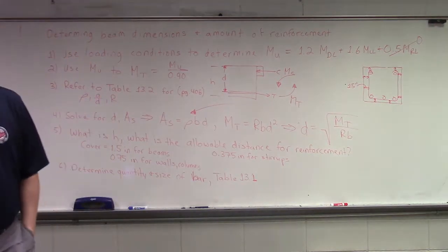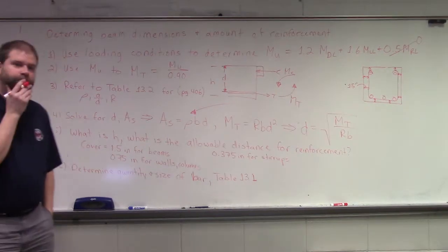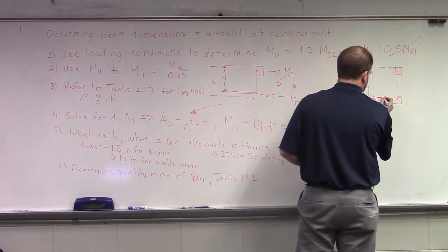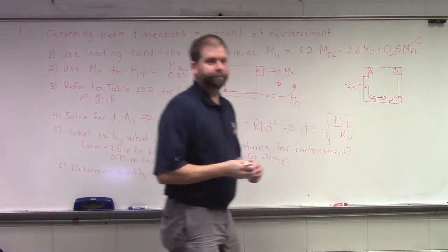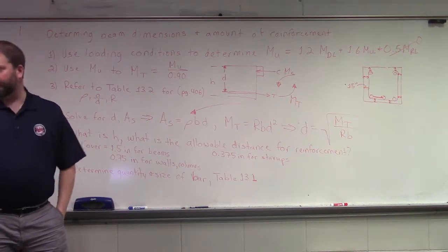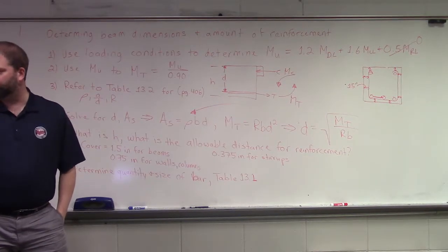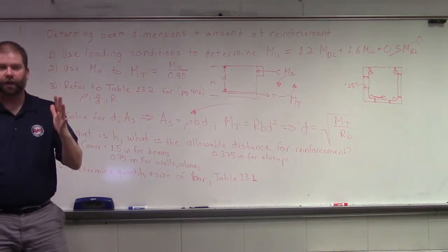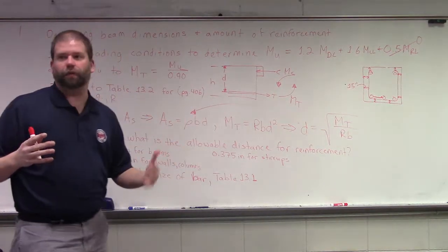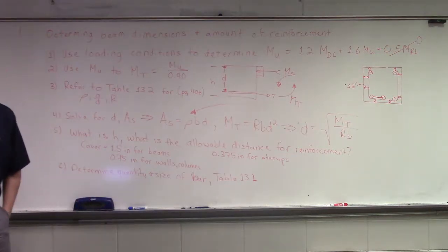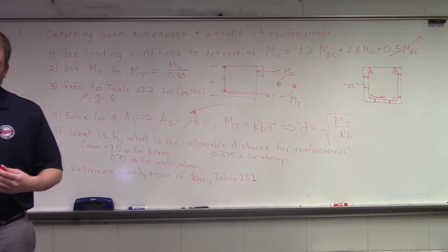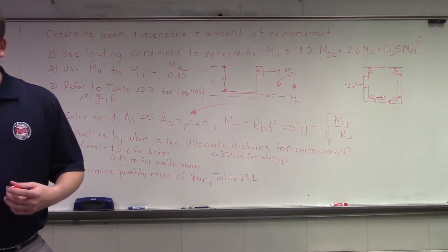So what Steve was saying is, whatever your bar diameter is should be at least your separation. Correct. Unless you're using a 3/8 bar or whatever. If you're using a tiny bar, you want to increase that distance. We want to increase that distance whenever we can, to make it easier for our ready mix producer to make their concrete. But there are times where we're not going to be able to make it easy for our ready mix producer, okay?